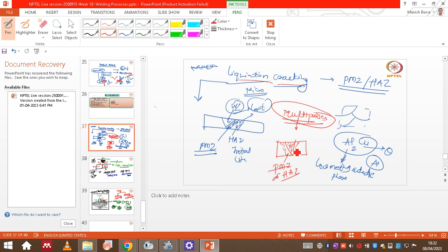So the main difference is that it is happening in the heat affected zone or partially melted zone because of the presence of low melting eutectic phases. The reason is the same, just these cracks are very small and can be observed only through microscopic observation, right? So what will happen is, if the material is solidifying, then the stresses will be acting at the last solidifying region, right?